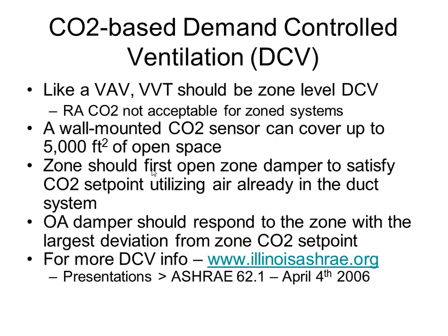And if you think about it, let's say you have just one return air CO2 sensor. If you have all of the people in your building normally in all of their offices, your return air should be normal. But if you take all those people and put them in one zone, that zone is going to be calling for outdoor air because it has high CO2 levels, but the unit's not going to know because the return air CO2 reading is going to be the same because you have the same number of people. There's not more people there than there were. So even though one zone requires outdoor air, the unit's not going to know that it needs it. So you need CO2 sensors in each zone locally.